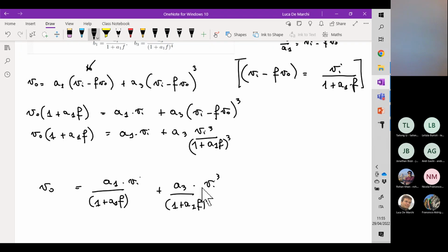We optimize the input and the output impedance. We can increase the input impedance and decrease the output impedance, which is very good for voltage amplifications. You can also use feedback to achieve the opposite effect, when you want to amplify currents, because in that case you want a very low input impedance and a very high output impedance. Another interesting effect is the bandwidth enlargement. So feedback is beneficial also in this sense.